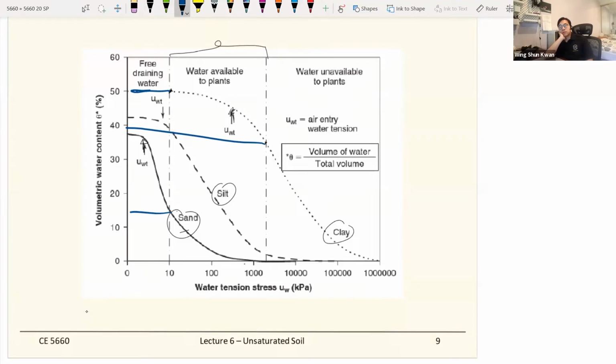There's also another way to look at it, for engineering purposes and geotechnical applications. If you want to build something like levees or dams, you realize that clay has much higher potential for stopping the water or preventing water seepage from the upstream to the downstream, because much of the water is stored in the body, and you also need much higher suctions to remove the water. Any questions?